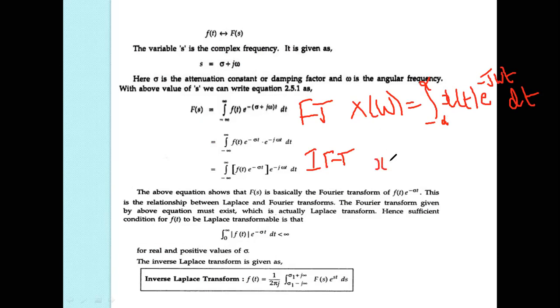Here x of t is equal to the integral from minus infinity to infinity, now with X of omega as input and the negative exponential becoming a positive exponential e power j omega t. Because the signal is a function of frequency, we apply the integration with respect to the frequency, whereas for a time domain signal we integrate with respect to time. And 1 by 2 pi also.